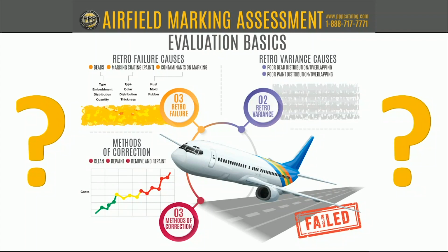I'll kick that one off. So there's really three things when you're talking about tip types. We're going to use the airless because that's the most common machine used in the airfield environment and really in the roadway environment now. So of course you have the brand, and the brand needs to match the machine or at least the tip guard of what you have on the end of your gun. So the brand is really predicated by the brand of either tip guard or machine you have. Then you have the type: is it a striping tip or is it an architectural tip? And we talked a lot about that. By far, striping tip is what you need to be using the majority of the time.